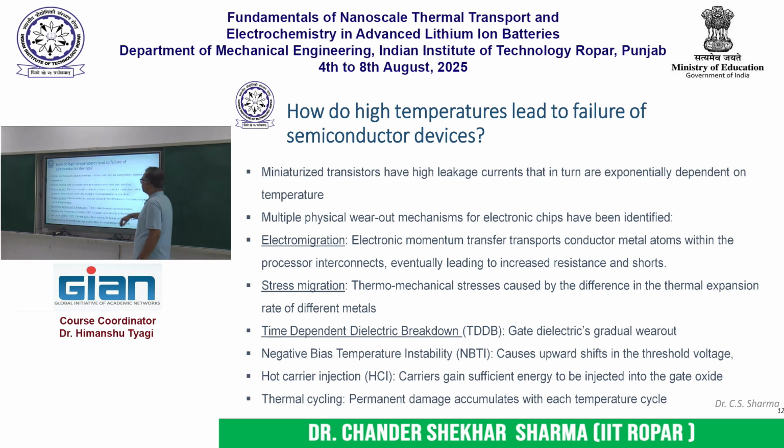Similarly, there can be thermomechanical stresses developed due to repeated cycling of high and low temperature, and that thermal stress can lead to delamination of different layers if the cycle amplitude is large, okay. Then there are also gradual wear outs of the gate material, like a prolonged exposure to high temperature, and there are a host of other mechanisms also, right. So electronic engineers always worry about this. So as thermal engineers, we have to take care that the temperature of the device is below the specified temperature limit during the lifetime of the microprocessor,